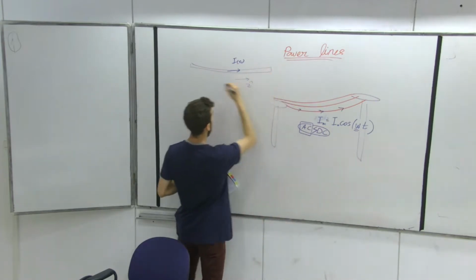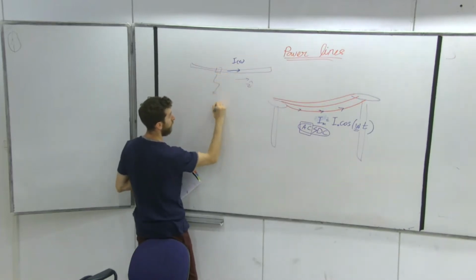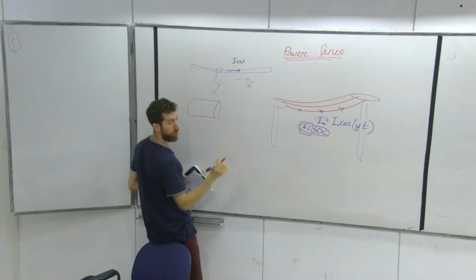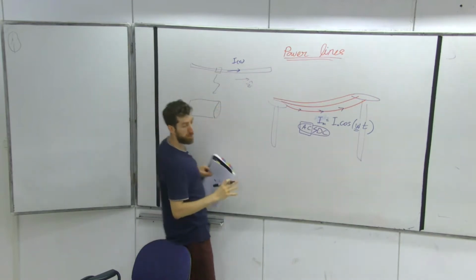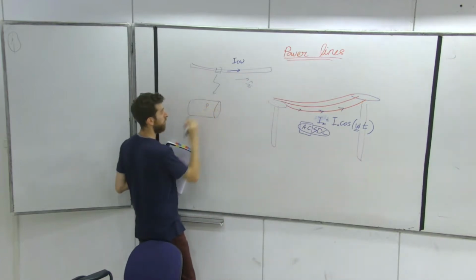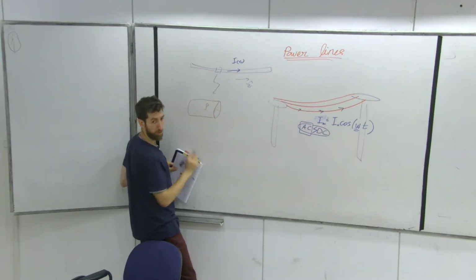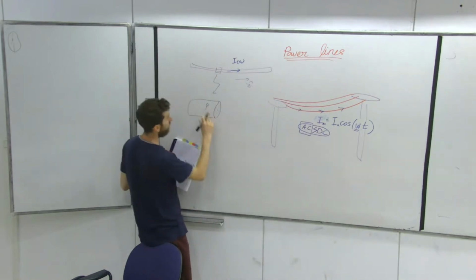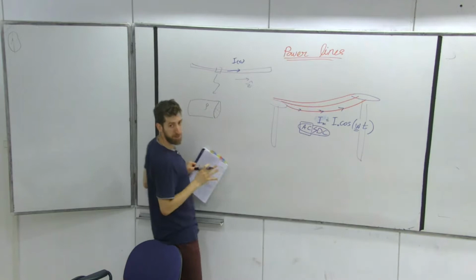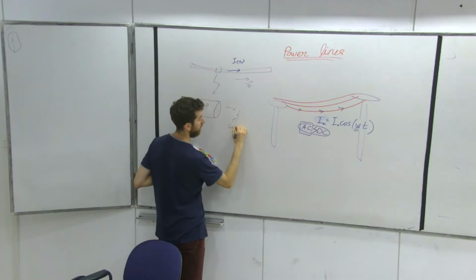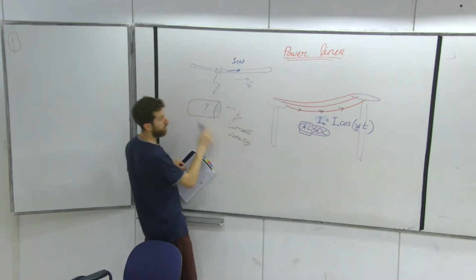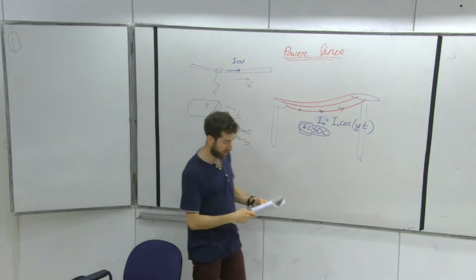Here, if I'm going to look at, let's zoom even more. So if I'm going to look at the cable, there's no difference at that point, at that point, at that point, whatever point that you like to look at, the properties of the materials are the same. It's rho. Remember, rho, the resistivity, perfect. And if rho is constant and everything is symmetrical, you can even say further the J, the current density, is constant. It's also given, so that's what we know about this cable line.